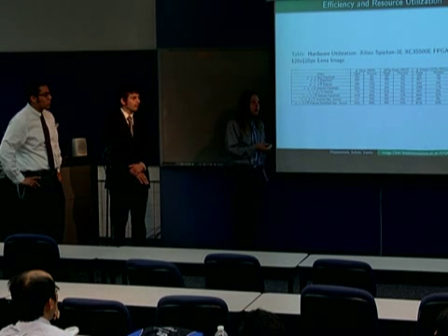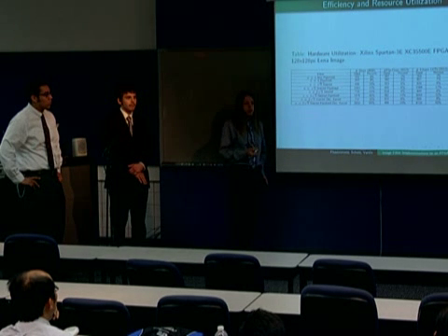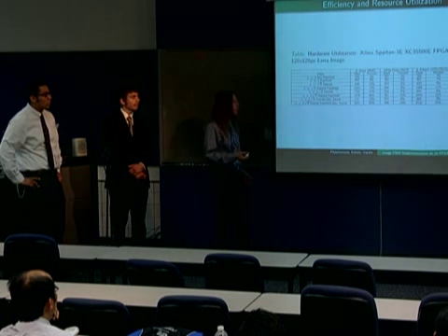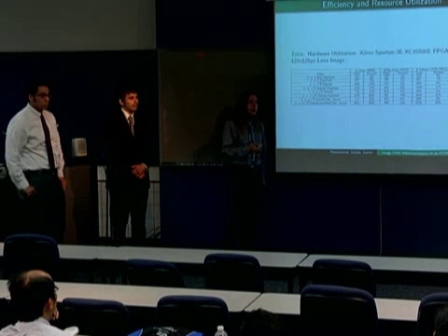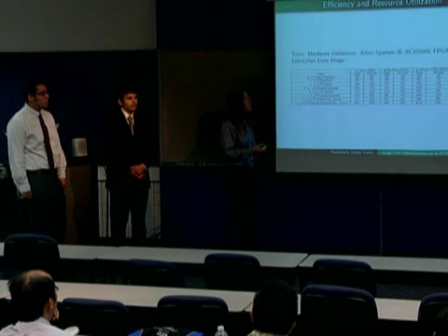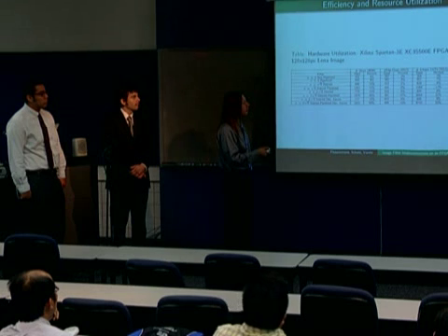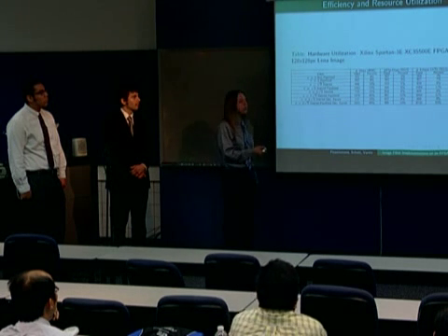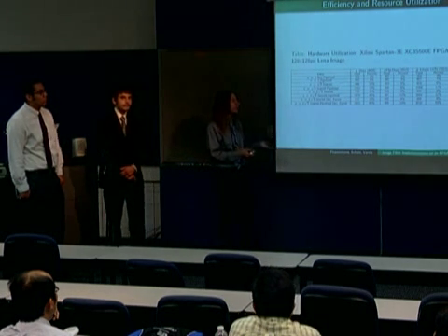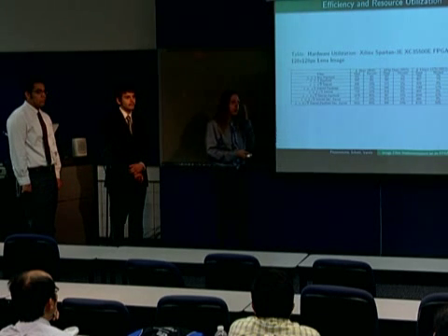Now, we didn't really worry about that because our target device is not necessarily the Spartan, but if we were to target it towards the Spartan, we could implement one of our multipliers through lookup tables, which would increase this resource column. But this is the second least used. So if we wanted to make it fit, we could just implement our multipliers as lookup tables rather than using the core multipliers.